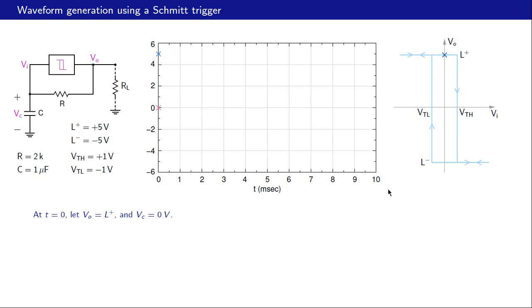This entire period is 10 milliseconds. Alright, so let us show this charging process. That is how the capacitor will charge. Since the time constant is 2 milliseconds, in about 5 time constants, that is 10 milliseconds, it would charge towards 5 volts. And the charging process would be almost completed. Now it doesn't quite reach there, and let us see why.